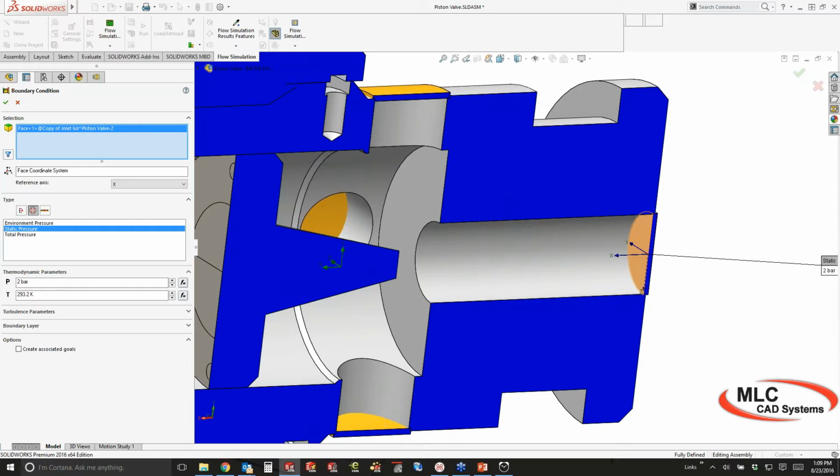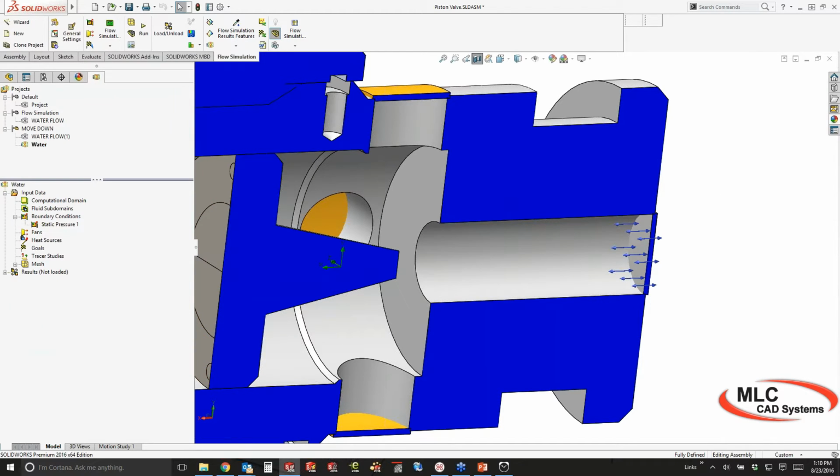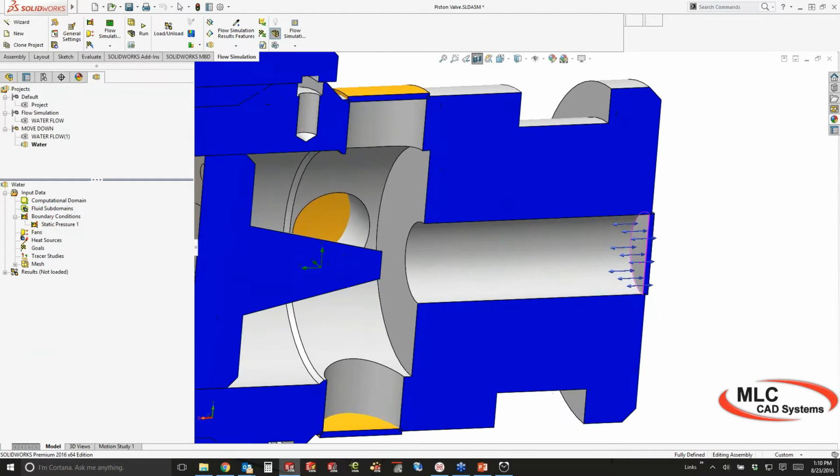So in SolidWorks Flow Simulation, in order to set up boundaries, I just put lids on everything. There's an automatic lid tool, but really just anything you have, just smash it on the front, and where it blocks that opening, that's going to be where the fluid is defined. So I don't have to model the fluid boundary. I simply have to cap off the areas of interest, and then those caps become my boundaries. So that's my first definition, which is the pressure opening here at 2 bar.